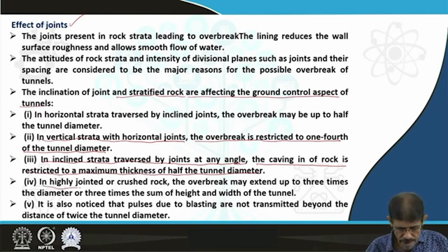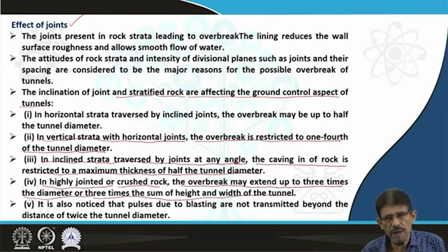However, in highly jointed or crushed rock, the overbreak may extend up to 3 times the diameter, or 3 times the sum of height and width of tunnels, creating a lot of problems and requiring some primary treatment before drill and blast, if the situation permits.